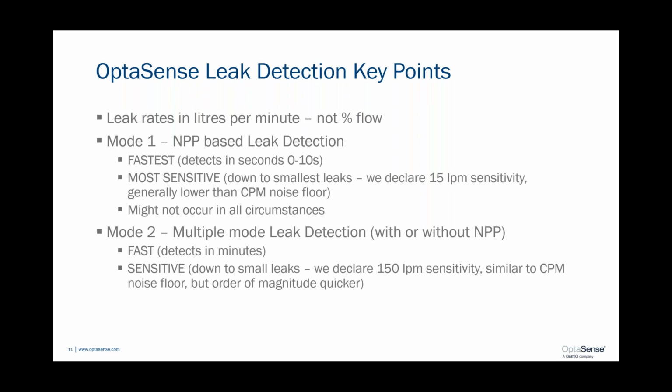We operate 2 different modes. Out of the 4 that I've shown you, the fastest and the most sensitive is the negative pressure pulse. It's a very unique indicator of a leak. We can deliver a result in tens of seconds, and it's very evident even for the very smallest of leaks.